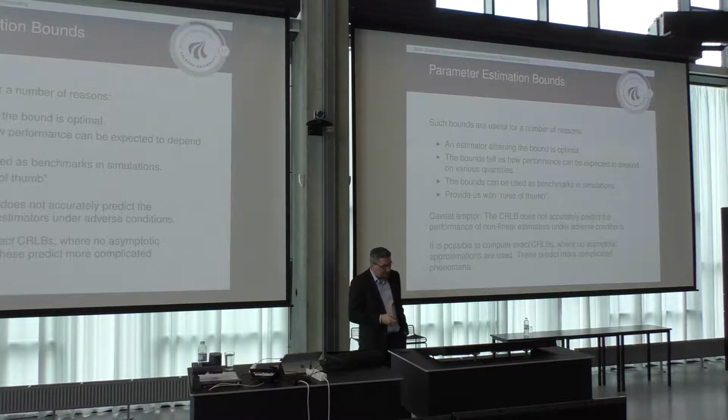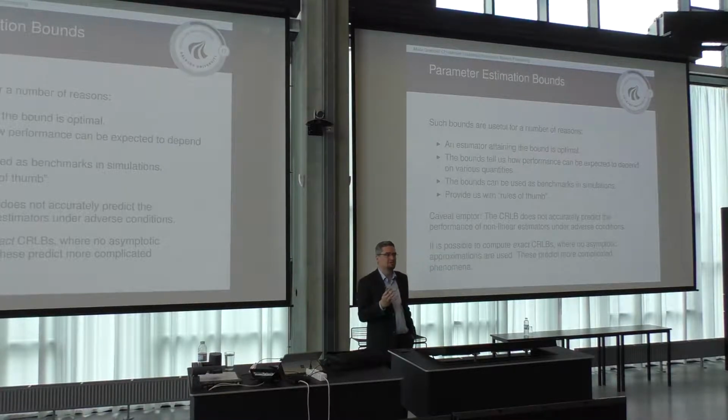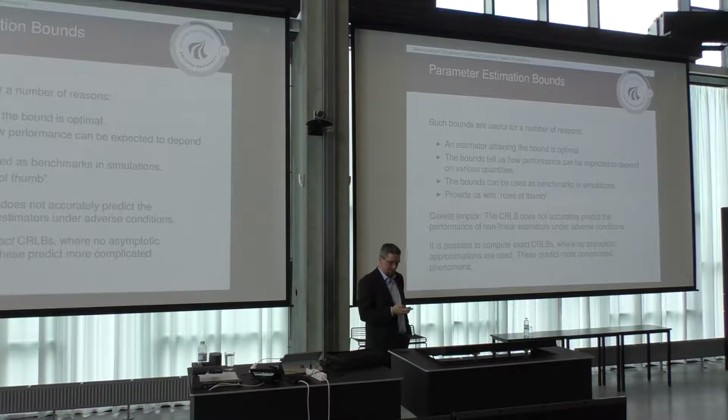One thing about this Cramér-Rao lower bound, or CRLB, is that it does not accurately predict the performance of nonlinear estimators under adverse conditions, what is called thresholding behavior. But it is also possible to compute what are known as exact Cramér-Rao lower bounds, where you don't make asymptotic approximations, which are some that I used before. And these actually do predict more complicated phenomena.